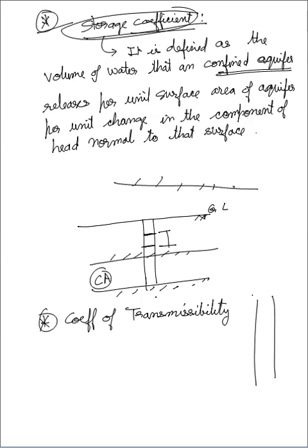Suppose you can see in 3 dimension, suppose this is a 3-dimensional column. It is a rate of flow of water through a vertical strip. This is your vertical strip, and its width is 1 meter. This strip and its length will be extending up to full saturation height.